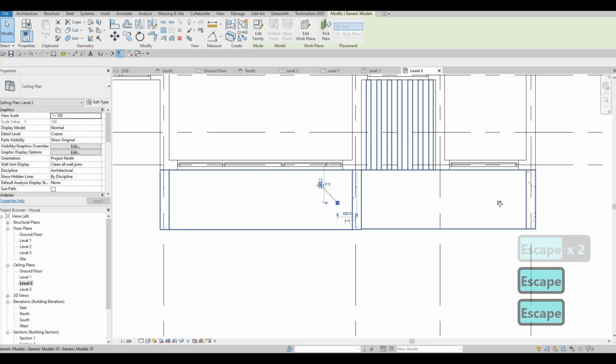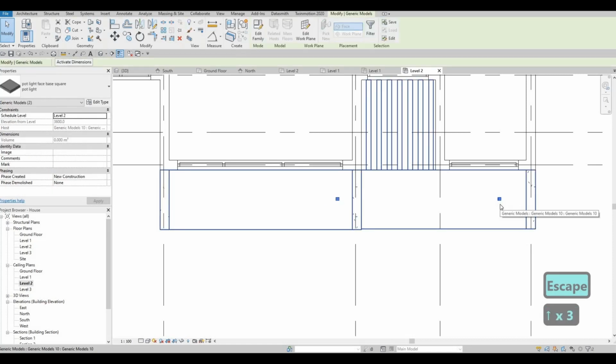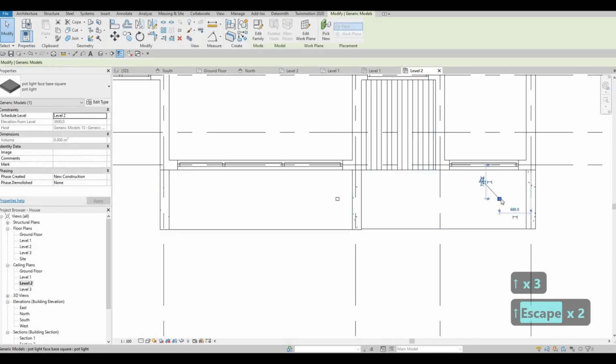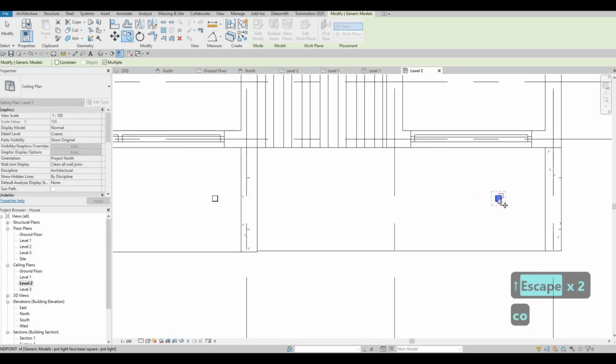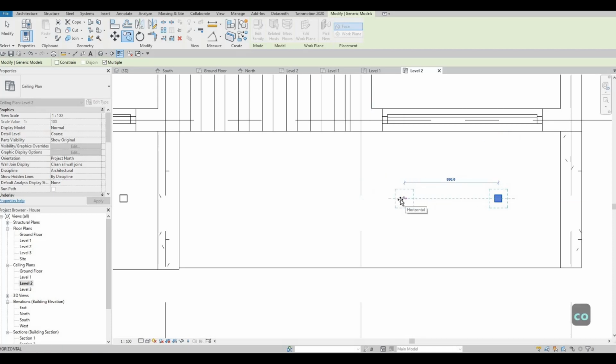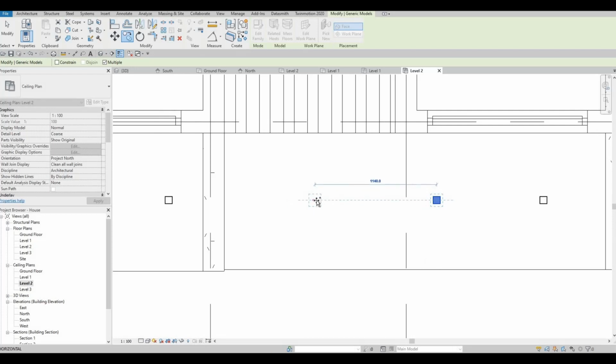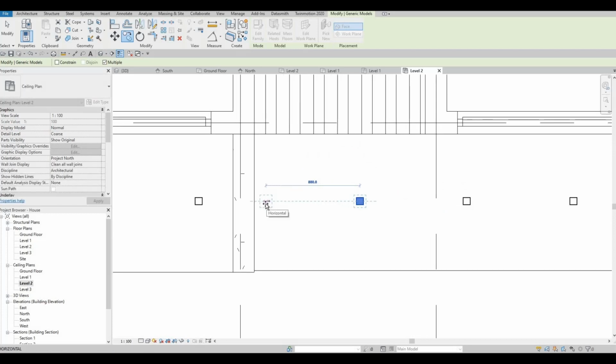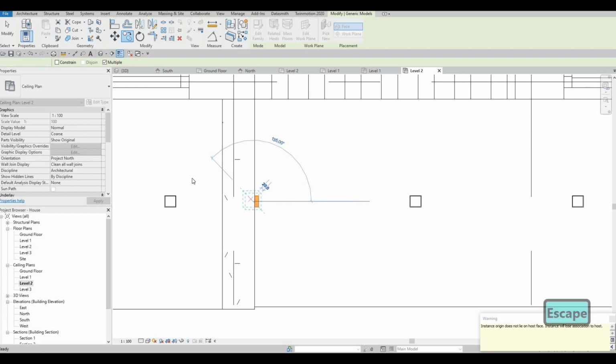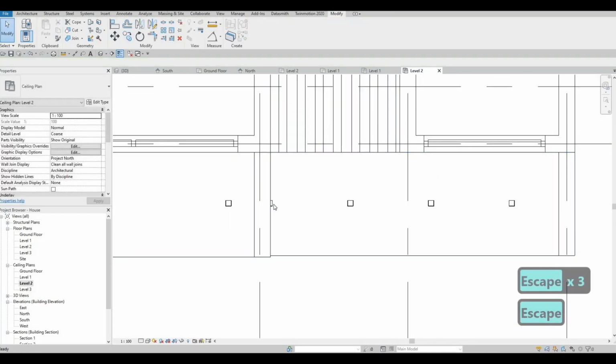So the family that I created is simple enough that you'll be able to add it instantly to any surface. Like I said, it's face based, because I don't like families that are wall based, ceiling based, and those kind of things. I'm limited to the category of the family. So that's why I created that instead.